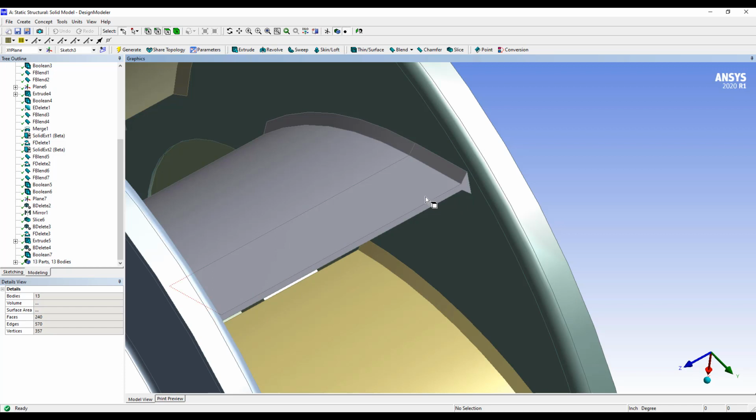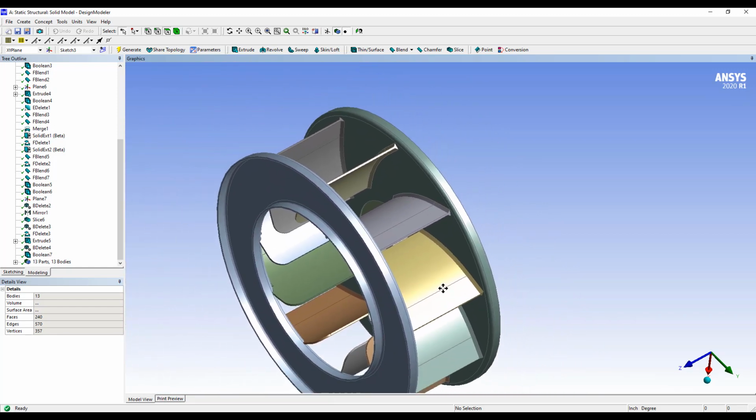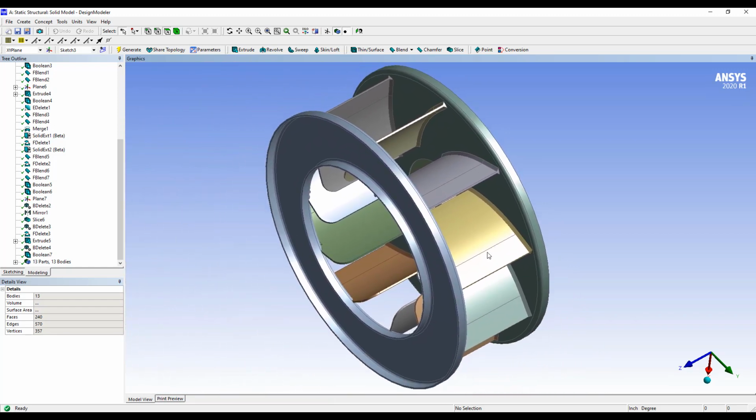You'll notice that the double-sided fillet welds are actually an integral part of the vane geometry. We're going to have to separate those as part of our modification process to allow us to do the seam weld analysis. So the intent here is to convert everything except the hub into surface bodies so we can use shell elements and leverage the seam weld capability in nCode DesignLife.